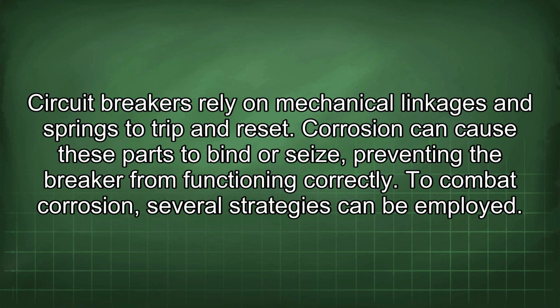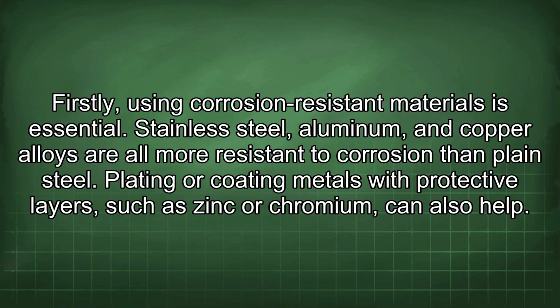To combat corrosion, several strategies can be employed. Firstly, using corrosion-resistant materials is essential. Stainless steel, aluminum, and copper alloys are all more resistant to corrosion than plain steel. Plating or coating metals with protective layers, such as zinc or chromium, can also help.